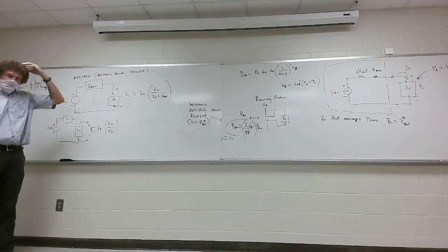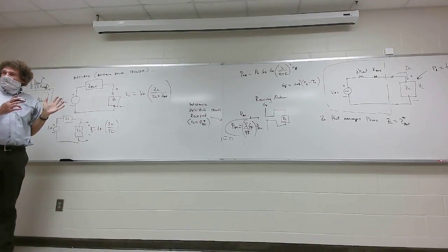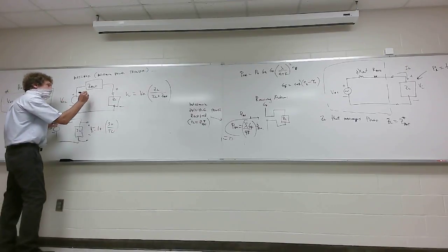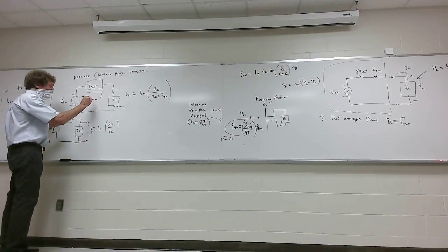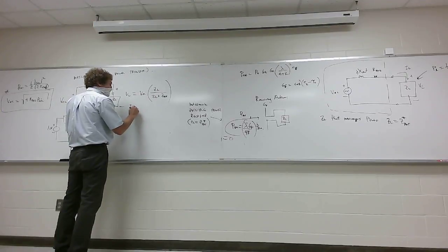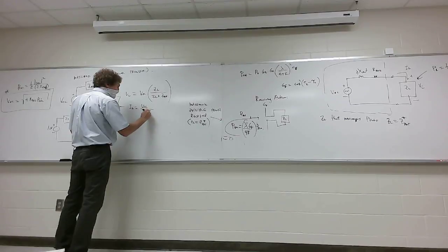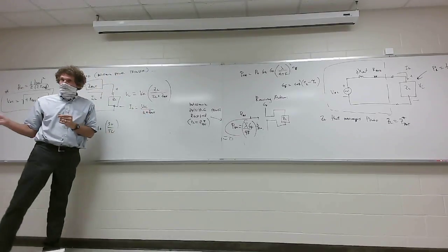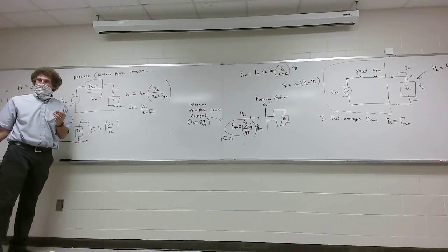Now, that would be the voltage, right? That's peak voltage, magnitude, and phase, right? How would we get the current? It's as obvious as it looks. We'd say I through the load would be V open circuit divided by ZL plus Z antenna. Do you agree with that? Right? With me? And if I wanted the power dissipated by the load, what would I do?